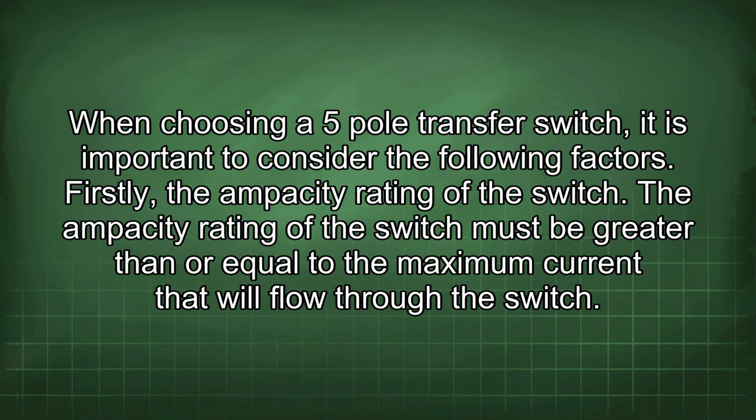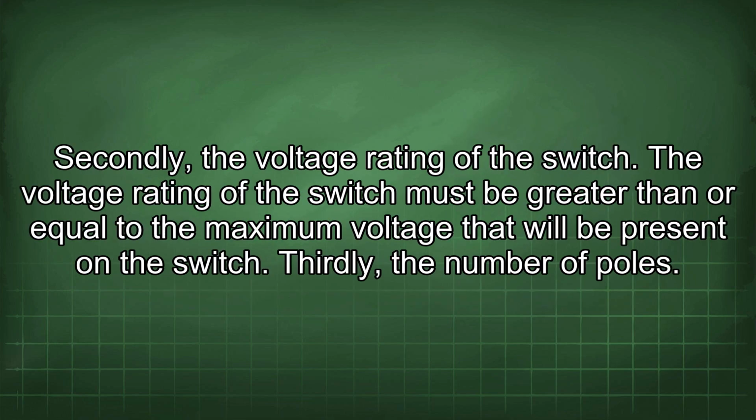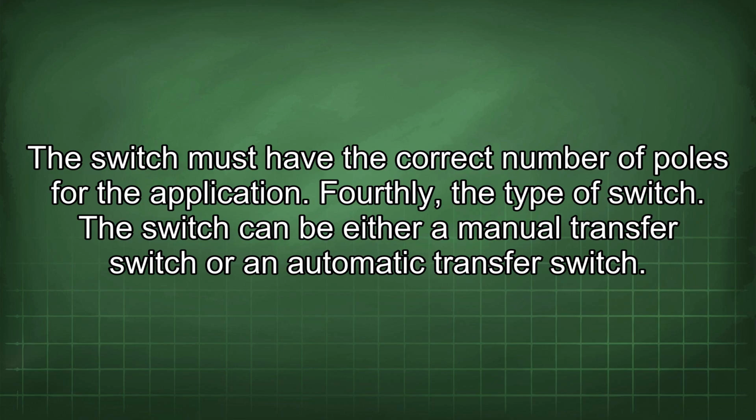When choosing a 5-pole transfer switch, it is important to consider the following factors. Firstly, the ampacity rating of the switch. The ampacity rating of the switch must be greater than or equal to the maximum current that will flow through the switch. Secondly, the voltage rating of the switch. The voltage rating of the switch must be greater than or equal to the maximum voltage that will be present in the switch. Thirdly, the number of poles. The switch must have the correct number of poles for the application.